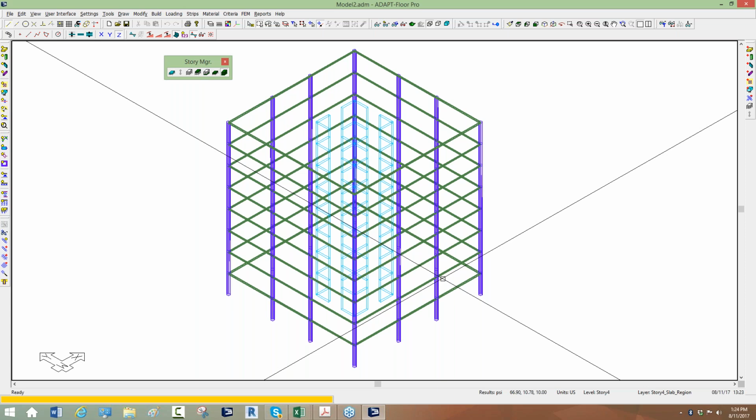The tributary load takedown tool has really nothing to do with finite elements. It's purely based on a geometrical algorithm that allows the program to subdivide the frame into tributaries, and it produces global takedown results for columns and walls. The usefulness of it might be to collect service loads for sizing foundations and columns. Within just a few weeks, it could be used to design walls, to get preliminary wall designs.